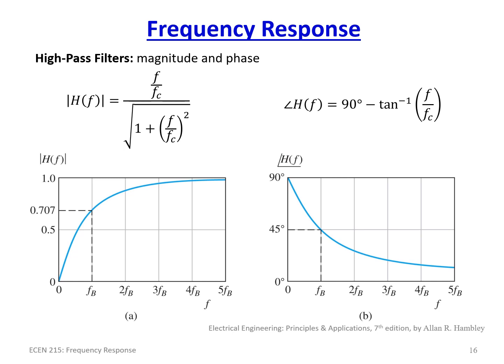Notice how the phase shift occurs as we go from 90 degrees, and it will eventually asymptotically reach 0 degrees. And the magnitude is about 0.707 at the cutoff, which is known as the 3 dB point, which we'll cover in another topic. And you asymptotically reach 1 as the frequency eventually goes all the way up.